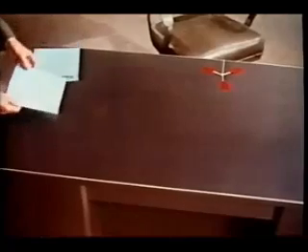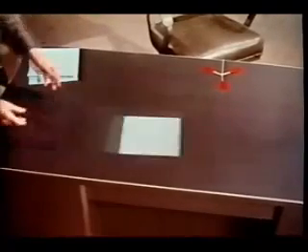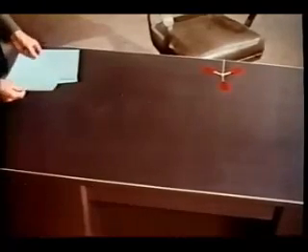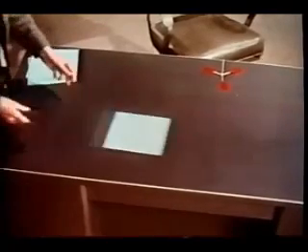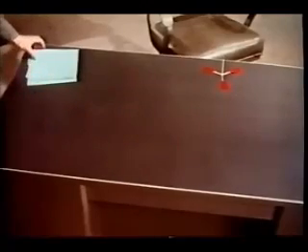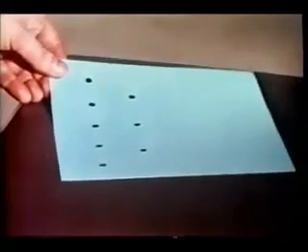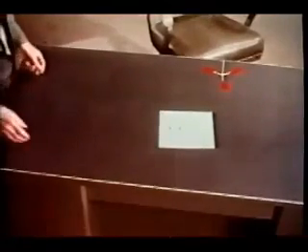As it settles, the air is forced out of the narrow space between it and the table. The tangential stress so produced enables enough pressure to be built up beneath the notepaper to support it for a time. And during that time, the friction retarding sideways motion is very small. If a few holes are made in the sheet so that the air can escape without passing under its outer edge, it stops much more quickly.